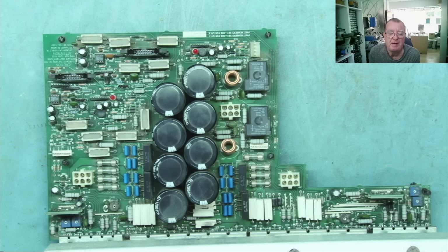More likely to fail, for example, on amplifiers where you have a plus and minus 95 volt rail and the manufacturer fitted 100 volt rated capacitors. So yes, a 100 volt rated capacitor can probably handle 110 to 120. There is some tolerance in there, but they're being pushed very close to the limit. And gradually with age, they are more prone to failure.